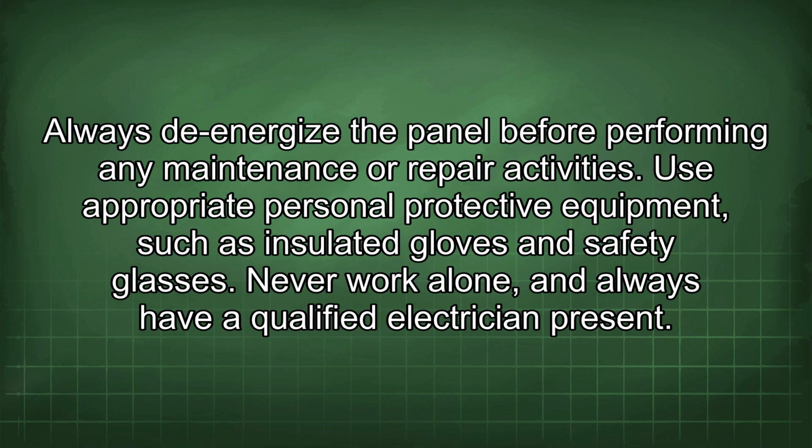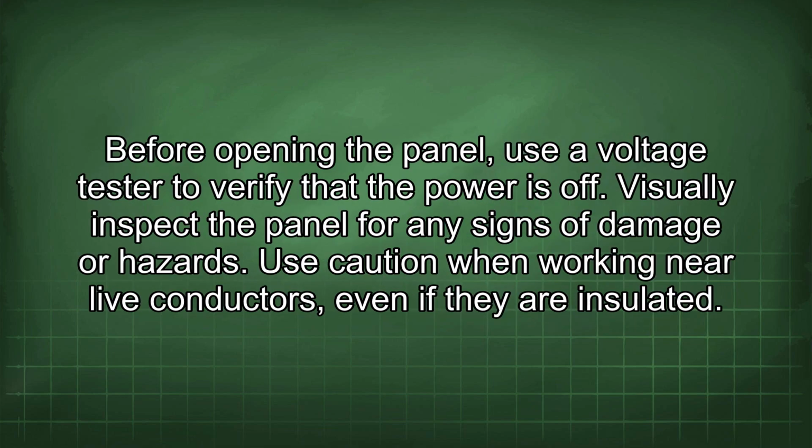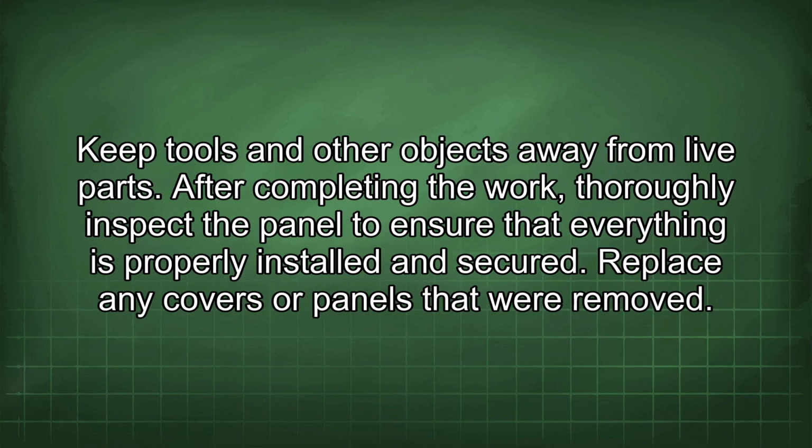Always de-energize the panel before performing any maintenance or repair activities. Use appropriate personal protective equipment, such as insulated gloves and safety glasses. Never work alone, and always have a qualified electrician present. Before opening the panel, use a voltage tester to verify that the power is off. Visually inspect the panel for any signs of damage or hazards. Use caution when working near live conductors, even if they are insulated. Keep tools and other objects away from live parts.